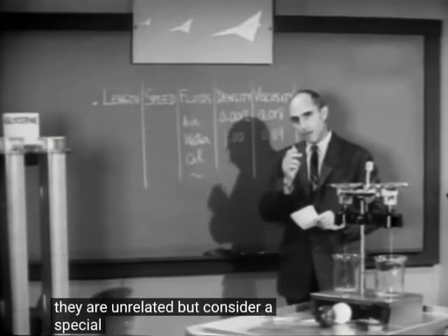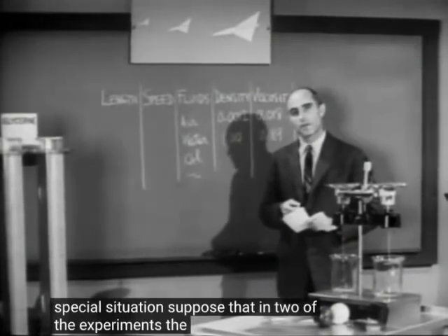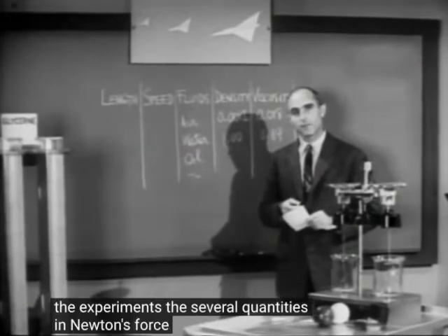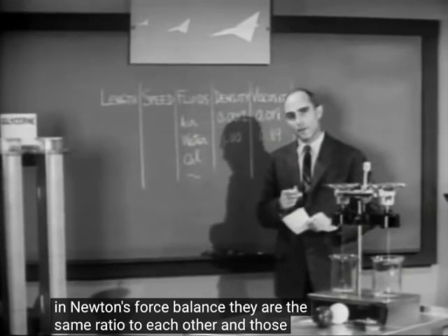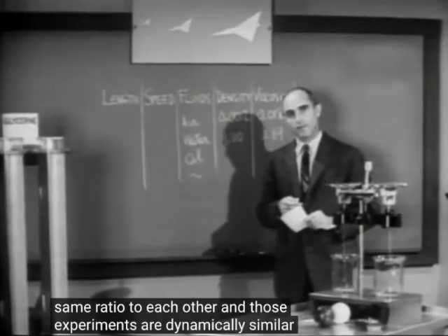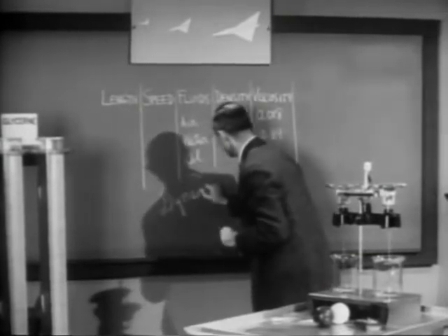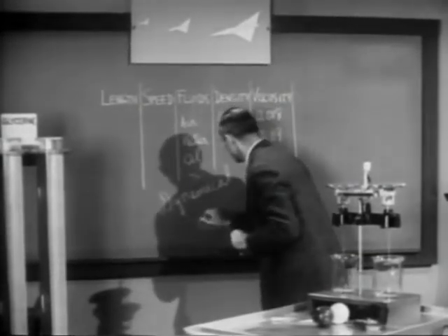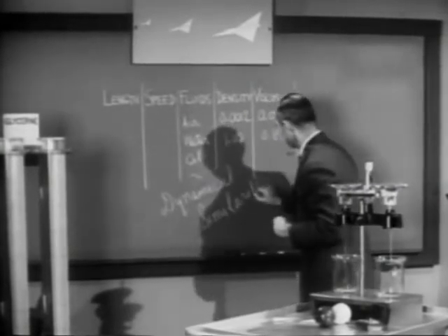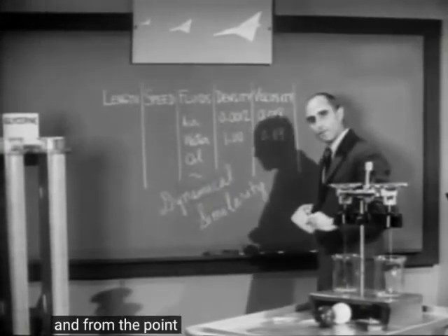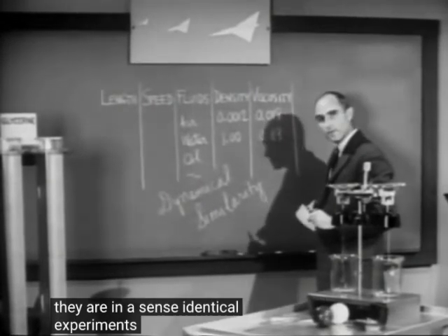But consider a special situation. Suppose that in two of the experiments, the several quantities in Newton's force balance bear the same ratio to each other. Then those experiments are dynamically similar. And from the point of view of mechanics, they are in a sense identical experiments.